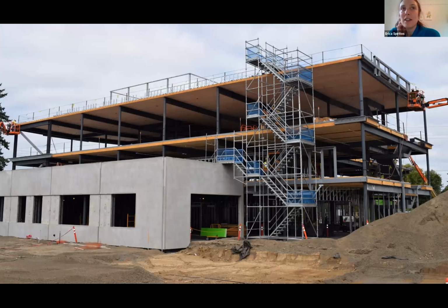Here's a hybrid structure, CLT decks with steel frames. Similar considerations here around manufacturing tolerances. Also have to take into account trade sequencing and just coordination of the geometry of this structure. It's really helpful if one group could detail the entire structure for fabrication rather than trying to marry a timber fabrication level model to a steel fabrication level model by another modeling group.